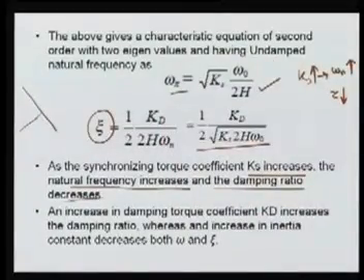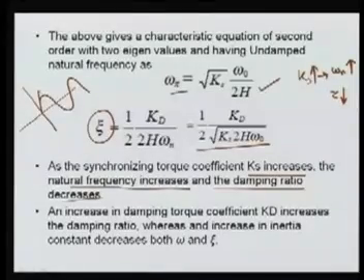So what is happening? It means the system is just oscillating. Now if Ks is increased, the frequency is increased and damping is reduced, meaning the system will be less damped, a very large frequency will appear, and again the damping will be less, so the oscillation lasts for a longer period.